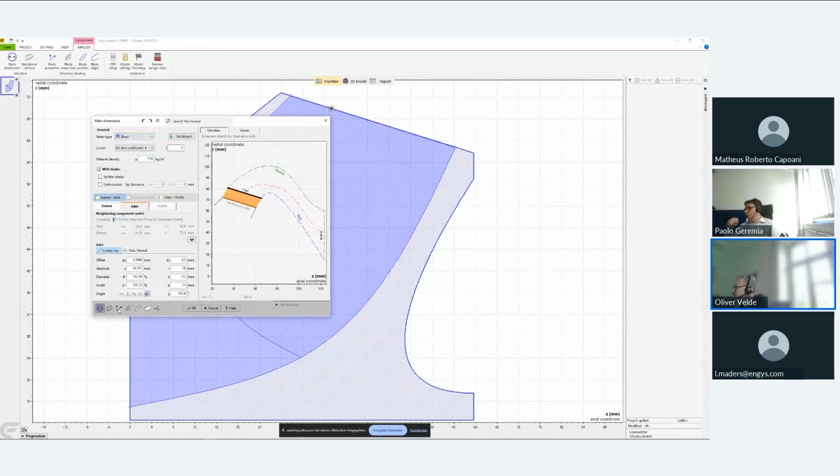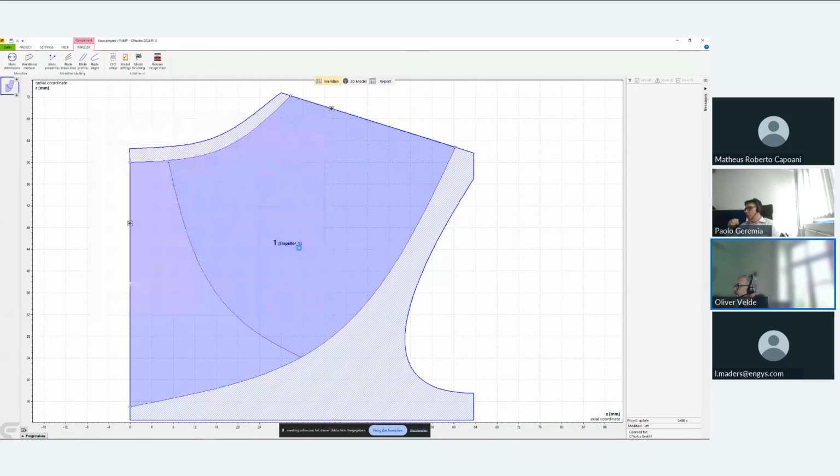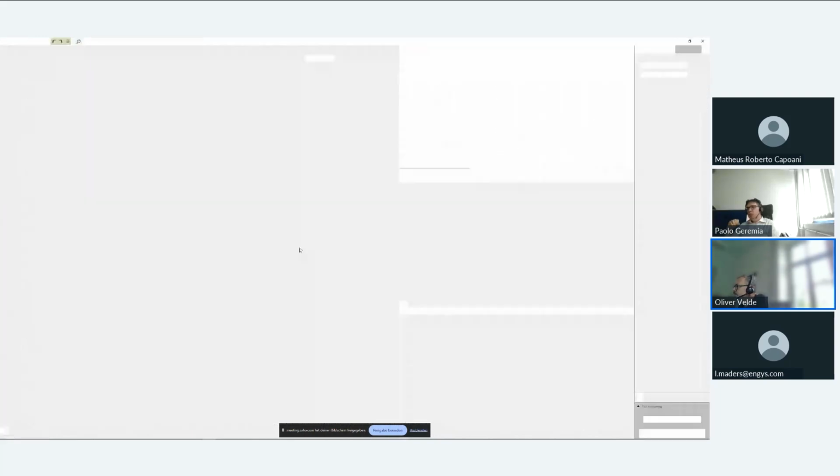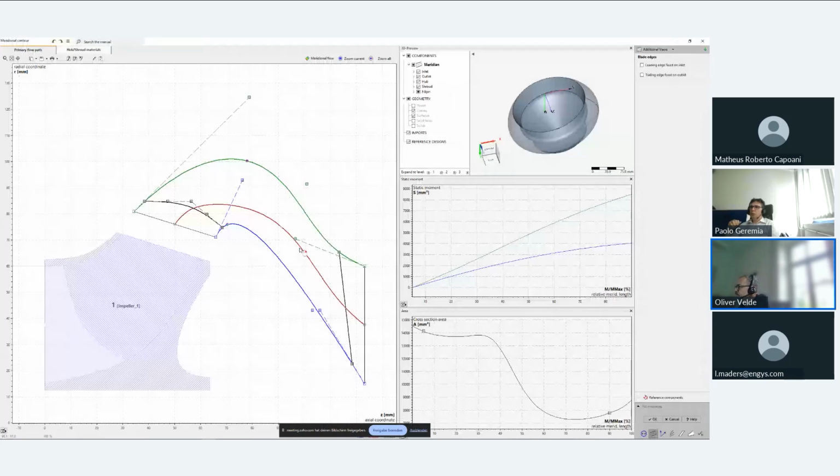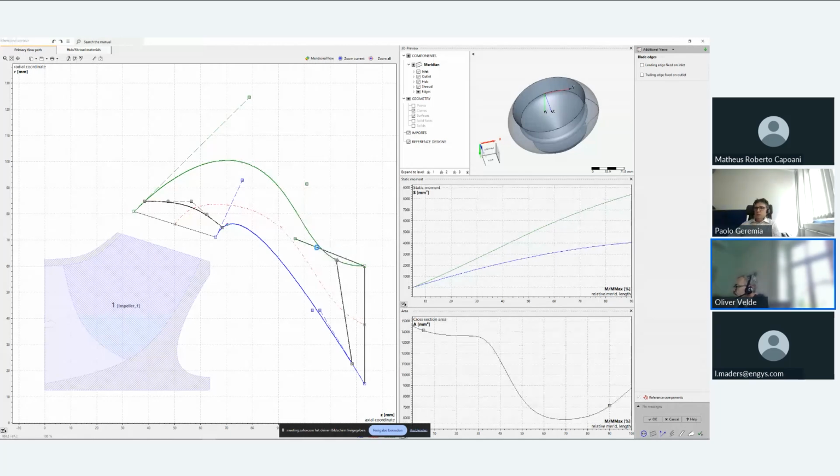The next step is very similar to the impeller design, the meridional contour design. Again, we have a predefined default setting of the control points. That's why we immediately see something at least familiar. Again, I can adjust this by right-click and getting access to other features. So, for instance, I want to have it horizontal at the outlet, so I'm going to add a 0 angle here.